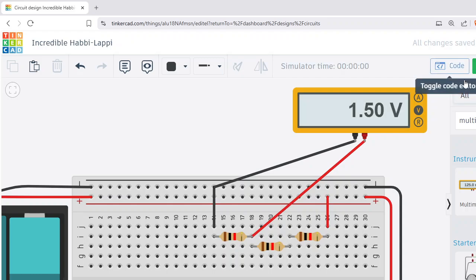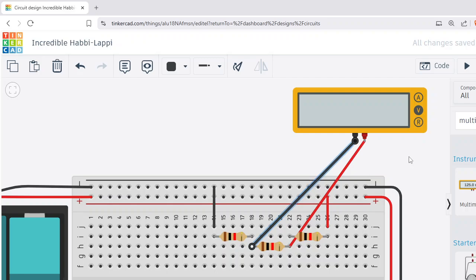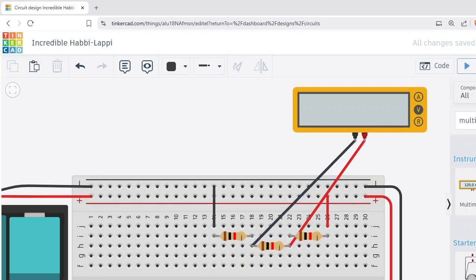1.1. 0.5 volts. Okay. What happens if I change this to this and change this to this? What is the voltage now? 1.5 volts again, because it is again divided, no? So across every resistance the voltage is going to be 1/3. So 1/3 of 4.5 is actually 1.5.